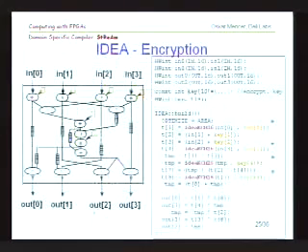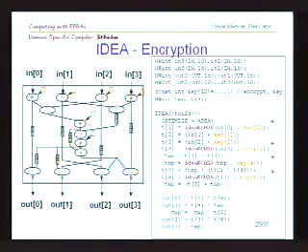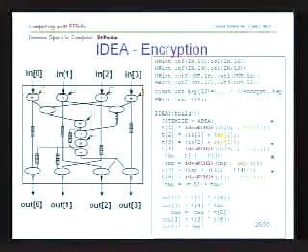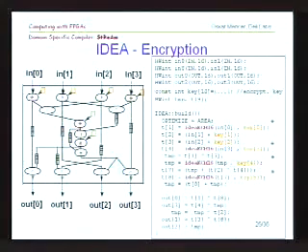Another example here, a little bit larger, is the IDEA encryption, where in the beginning I wrote many pages of RTL level code to create the IDEA encryption. Here I can just write a couple of lines of code that give me the full encryption, and I didn't even have to write this because the definition of the IDEA encryption algorithm is in C, and you just get it down from the web. All you need to do is change the types to basically set which variables have which functionality in your architecture, and it compiles down into that architecture just by compiling it with a GNU C++ compiler.